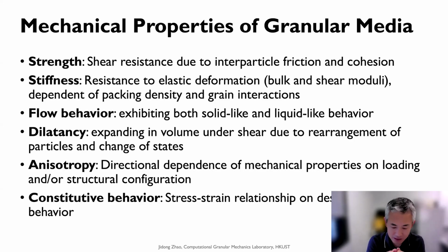Dilatancy is a quite interesting thing that is basically unique to frictional materials: when we shear granular material, the shearing stress can not only generate a shear strain, but also generate volumetric changes. It typically refers to when we get a volumetric increase during shearing.